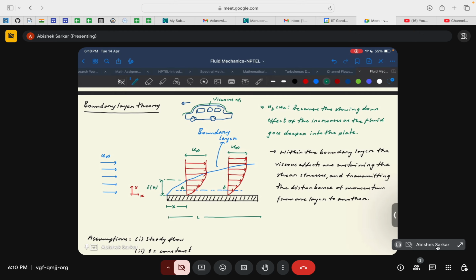So it will basically mean that in this region the flow would have rotational effects and viscous effects would be highly present. Okay, but there will be very steep velocity gradients. And beyond this region, in this outer region, the flow can essentially be modeled as potential flow. Potential flow, again, we have not discussed explicitly, but we have termed it again and again while discussing fluid dynamics and fluid kinematics. So potential flow basically means that the viscous effects are negligible, or inviscid flows.